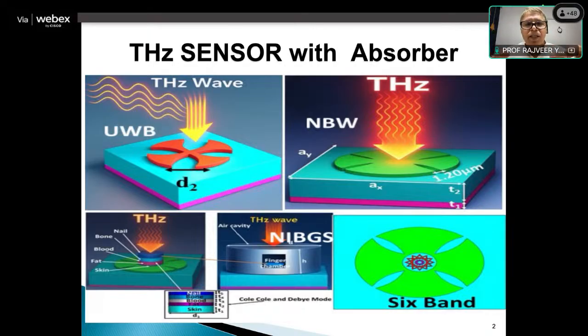And then based on those reflected wave and transmitted wave, we compute how much is the absorption, because the absorption is specific to the molecular wavelength of glucose, which has C6, H12, and O6. In this glucose molecule, there are 2 covalent bonds. One is OH and another is CH. OH is similar to water, so we are not able to get that much reading in OH. So we like to target CH covalent bond and then create resonance.